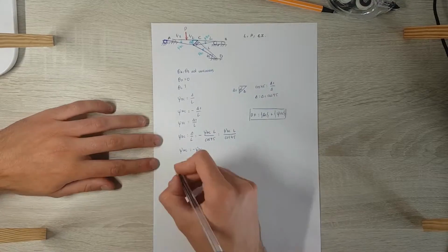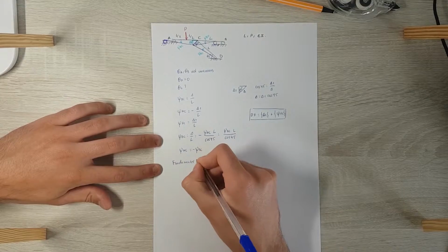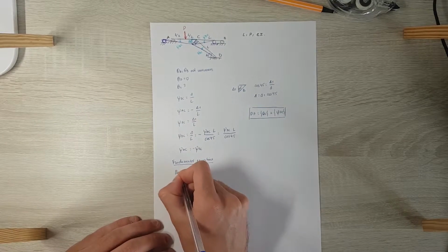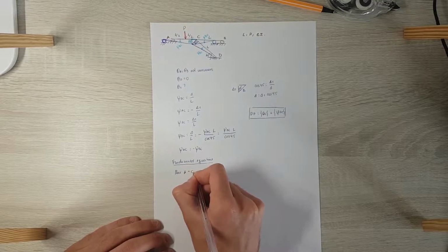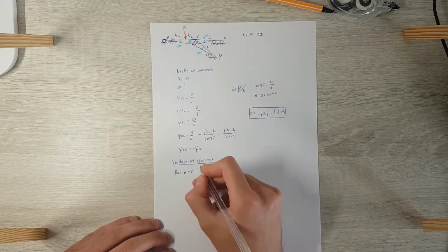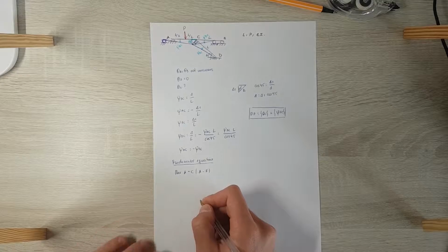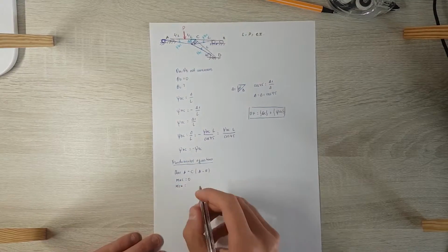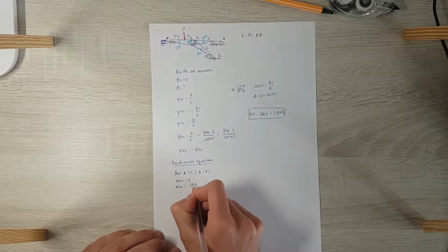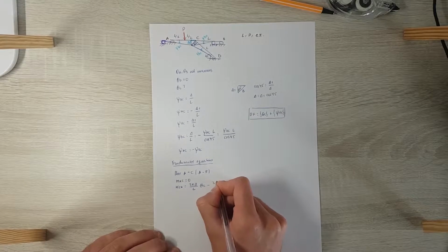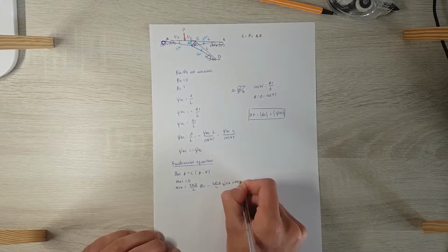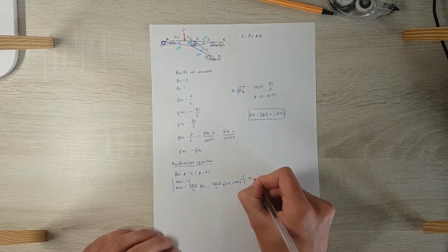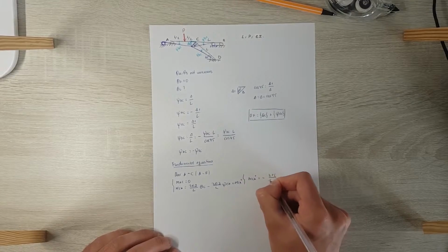So now I'm going to write the fundamental equations of the system. First I'm going to start with the bar AC, which is articulated fixed. So the moment AC will be 0 because A is articulated, and the moment CA is given by this formula. And we have here the moment created by the external load P, which is minus 3PL divided by 16.